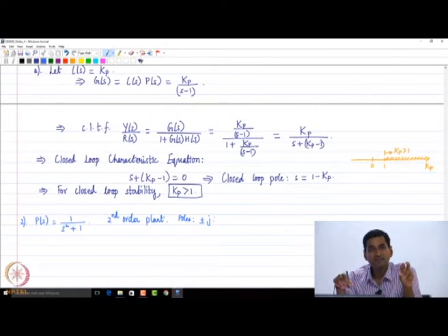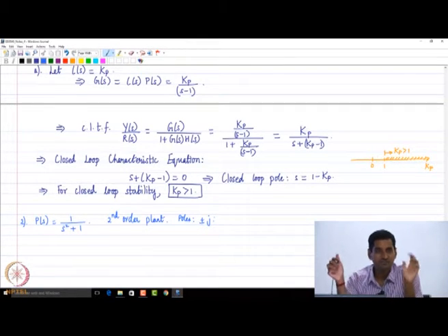what will happen is that if I provide a sinusoidal input whose angular frequency is equal to the magnitude of the pole, the corresponding output essentially goes to infinity in magnitude as time progresses. So if you provide cos t or sin t to the system, the output essentially blows off to infinity.